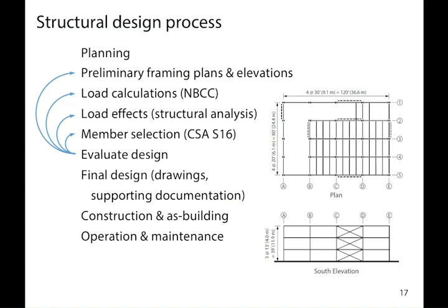And then throughout the construction process, the contractor is going to be responsible for retaining some professionals to document what happens on site, especially if they built something differently than what was planned. It happens often. You run into issues in the field, they're trying to build something, and it doesn't work out the way that they thought, so they make a change in the field, and you have to document that. And sometimes the engineer will take responsibility for it, sometimes they won't, and it depends on the firm's risk tolerances, essentially.